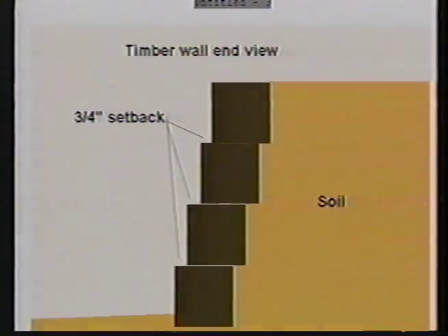When you encounter corners, plan to overlap each course as you build the corner. Carefully measure and cut the desired angle to ensure a smooth, tight joint. Toenail and spike each corner joint as you go.